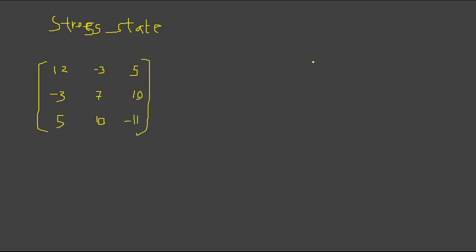So these have been given actually like a cube, right? You can imagine the sigma xx is 12, sigma yy is 7, sigma z is 11, actually it's a compression. Tension is positive, so it's the other way, minus 11, right? Sigma xy, so xy is this one, these shear stresses is 3, right? And this is sigma xyz. So these are some stress state. So now you need to find the stress invariant, right?